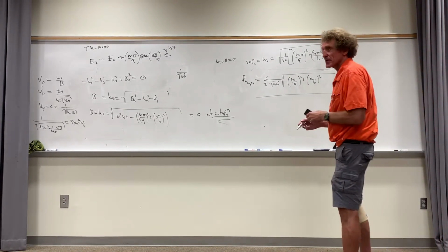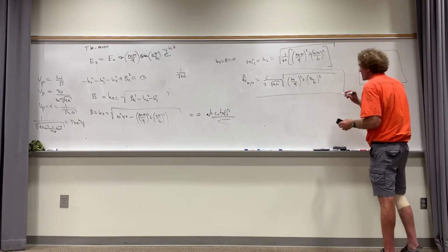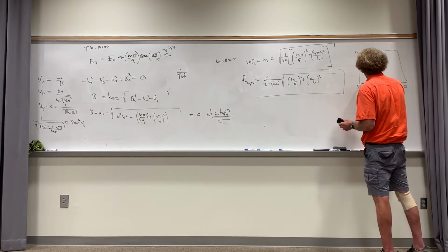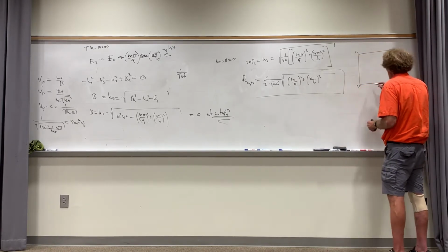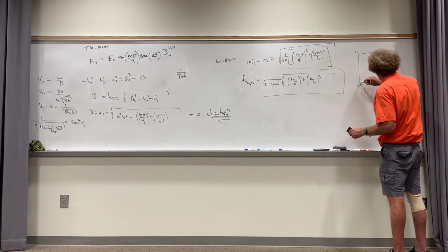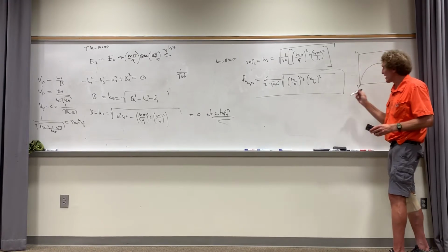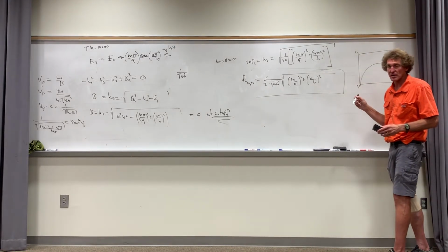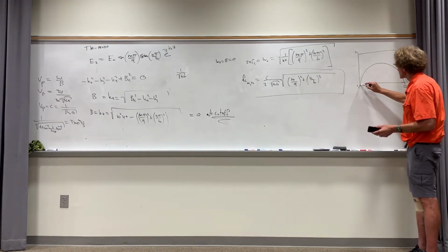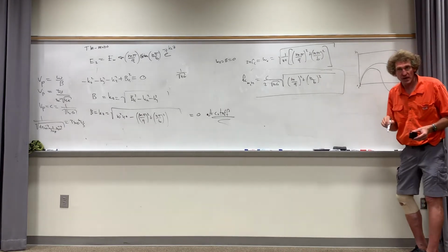All right, here's something about this too. I didn't say this, but when you look at waveguides, here's what really happens. In the lowest order mode, if this is a and this is b and this is 0,0, and this is the x direction, when you look at the modes, if you just wanted to look at the variation in x, it would be a perfect half sine wave right there. And it would have no variation in y for a 1,0 mode. If it was a 2,0 mode, then you would get this, like that. You get a full sine wave for a 2,0 mode.